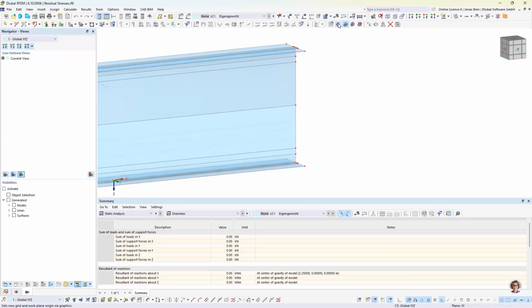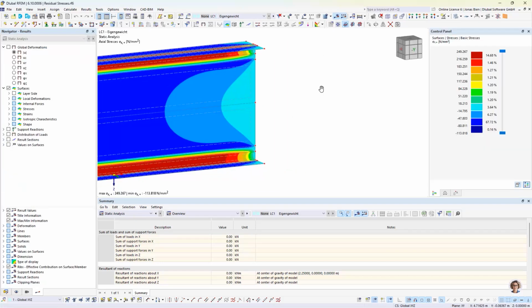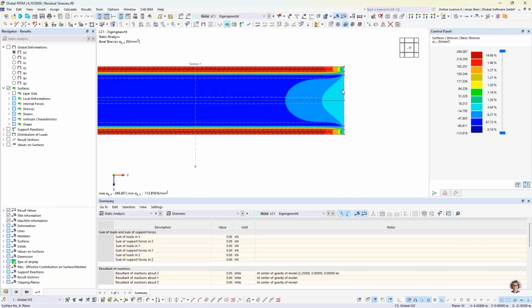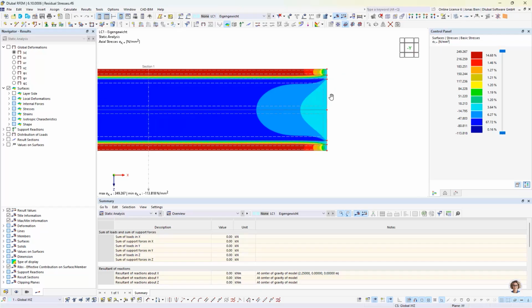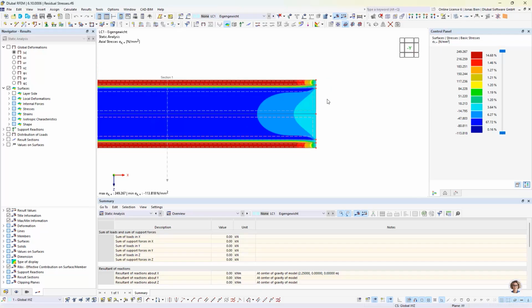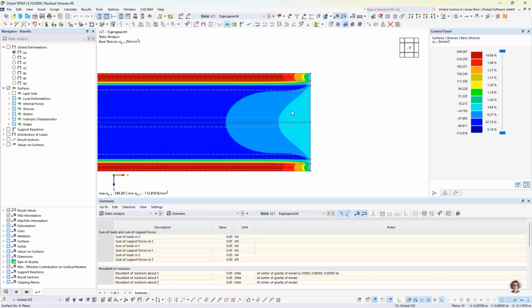And we can see that this has a great influence on the resulting stress state. So here, where we have more or less a disturbed state, where movement is free in X direction, you can see that those residual stresses actually vanish, and they diminish here at this free edge. But basically, this is what happens in reality as well.